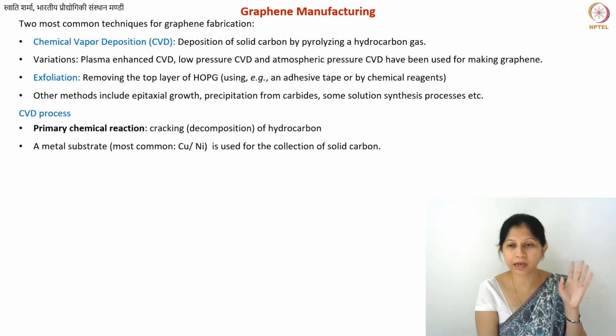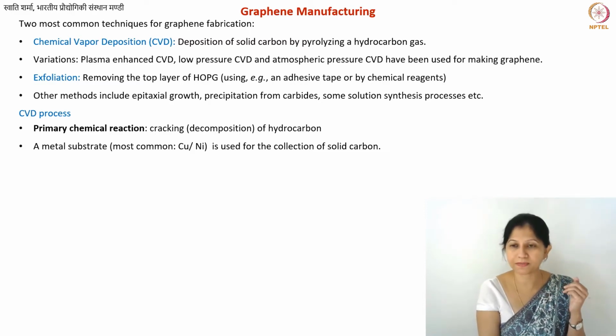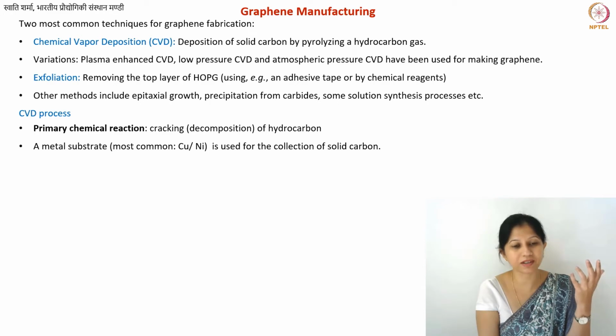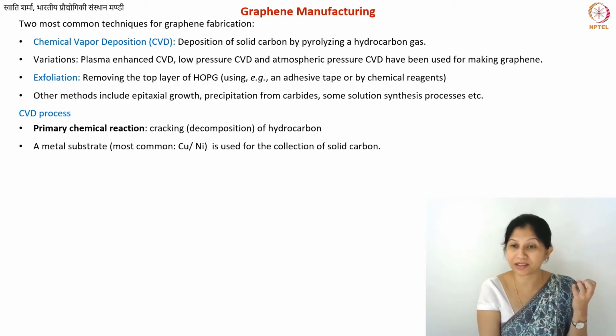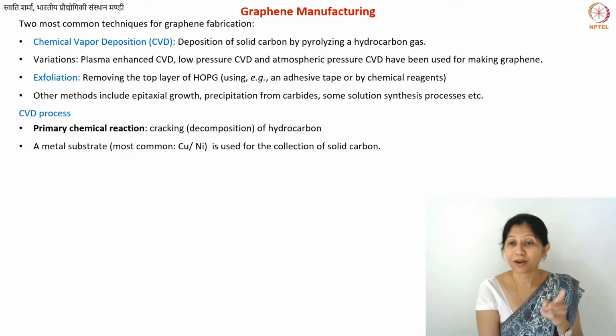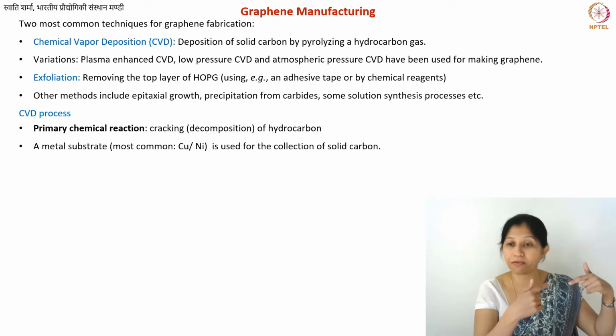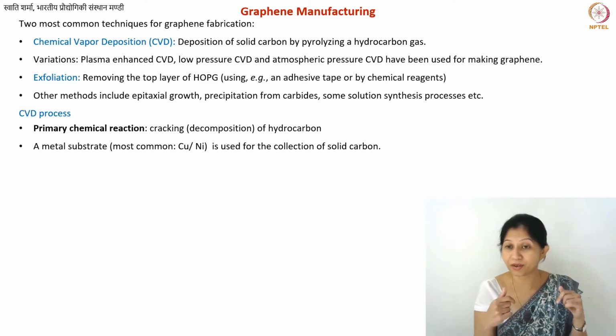When we were making needle coke structures, for example, needle coke to graphite, we did the first carbonization step, and then we had a lot of pores in our structure. We filled resin or pitch inside those pores, and then we carbonized it again and again to fill these pores. That pore filling can also be done using pyrolysis of hydrocarbon. So using the CVD process, you can take that pore containing structure, put it inside your CVD reactor, and then deposit layers of pyrolytic carbon inside your pores.